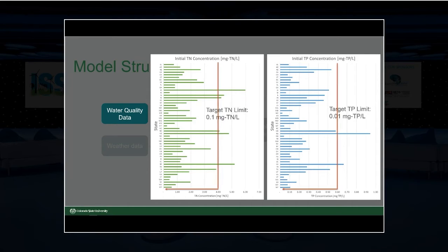So in the future, we need to receive reductions in total nitrogen and total phosphorus so that we can reduce the propensity of harmful algal blooms. But to facilitate this analysis across all states, we tested 2 low limits in the dilute nutrient range. So as water quality standards become more stringent, we need to estimate the costs associated by achieving these limits. This may seem like an absurd target, but attached algae systems thrive when nutrients are dilute, whereas conventional wastewater treatment technology is not likely to meet these target concentrations in an economically feasible manner.